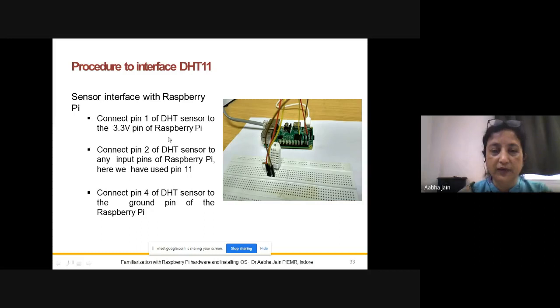As I mentioned in the video, though it was not very clear, the GPIO pin and the physical pin of the RPi are not the same. Physical pin number 11 is GPIO pin number 17. So you need to know which pin you are using.